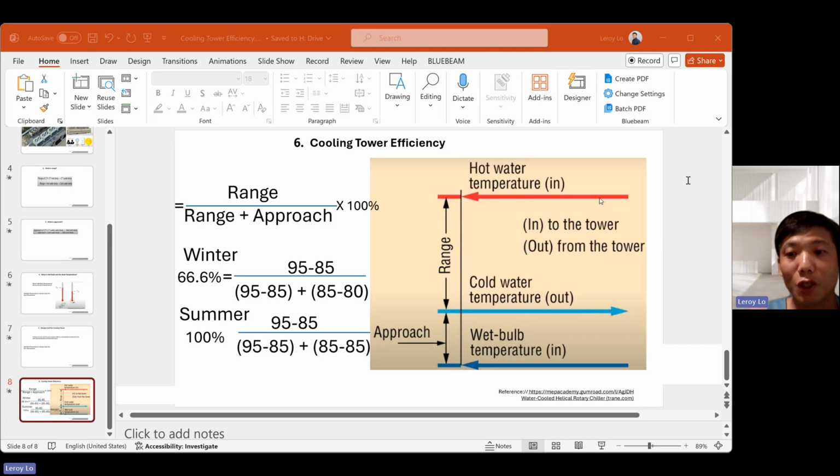At 100% cooling tower efficiency. So in practice, the cooling tower efficiency will need to be between 70 and 75. Normally, you need to account for the summertime. In summertime, you want to keep it at 70 to 80, maybe 85-ish. The ambient air wet bulb temperature rises in the summertime compared with the wintertime, so cooling efficiency limiting in the summertime is very common.